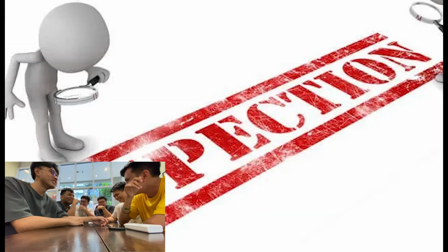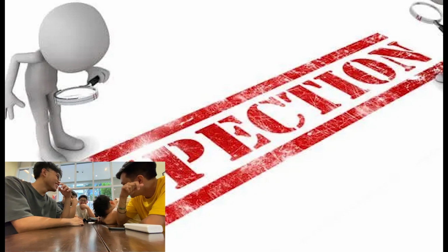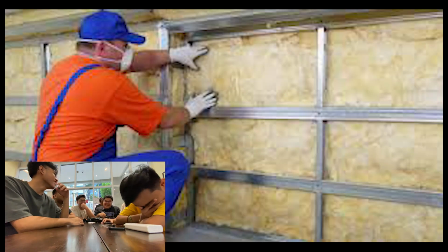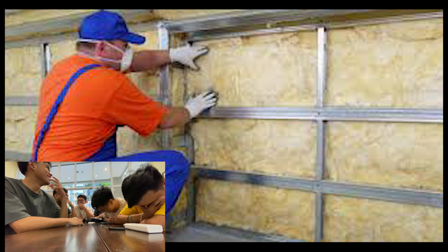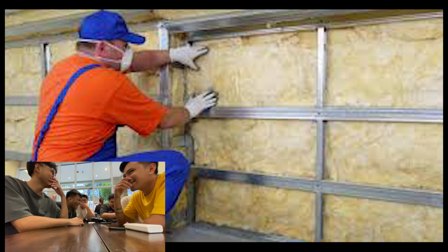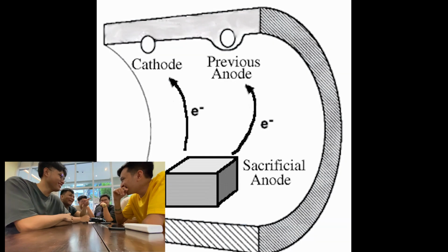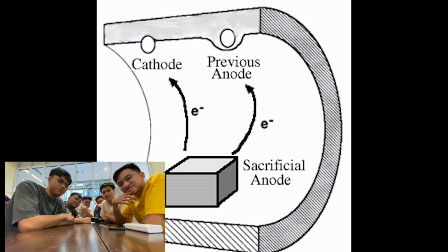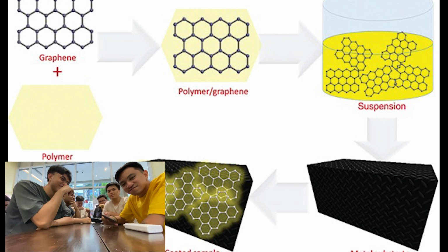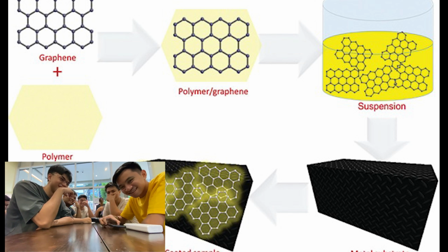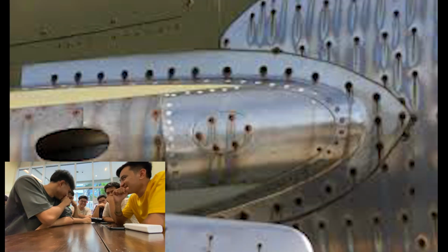Galvanic corrosion treatment. 1. Inspection. Identify areas where different metals are in contact. 2. Isolation. Use insulating materials like rubber or plastic washers to separate the metals. 3. Cathodic protection. Apply a sacrificial anode to protect the more reactive metal. 4. Coating. Ensure both metals are coated with a protective barrier. By understanding the types of corrosion and implementing appropriate treatments, the aviation industry can maintain aircraft safety and performance, ensuring they remain airworthy for as long as possible.